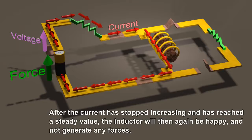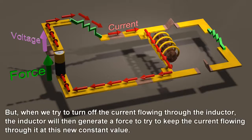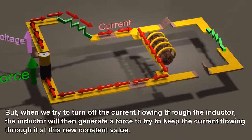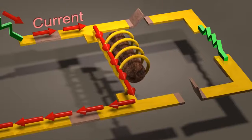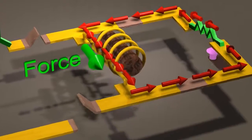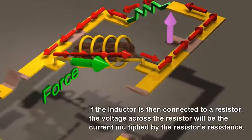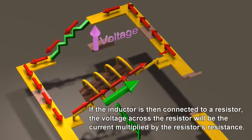After the current has stopped increasing and has reached a steady value, the inductor will then again be happy and not generate any forces. But when we try to turn off the current, the inductor will generate a force to try to keep the current flowing through it at this new constant value. If the inductor is then connected to a resistor, the voltage across the resistor will be the current multiplied by the resistor's resistance.